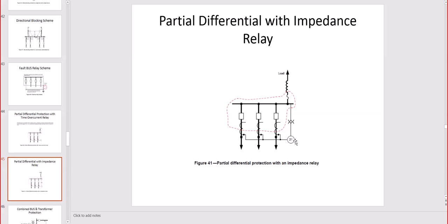We have 21 even on the standby generators and EPGs. We could have had it on the main generator. Somehow it was decided to put a 51V, which is looking at the overcurrent function with voltage drop when the generator trips, because a small current can still represent a short circuit at a lower voltage when the generator is tripped. But 21 traditionally is used for reading the impedance of the line in a certain direction. This is called the torque direction.